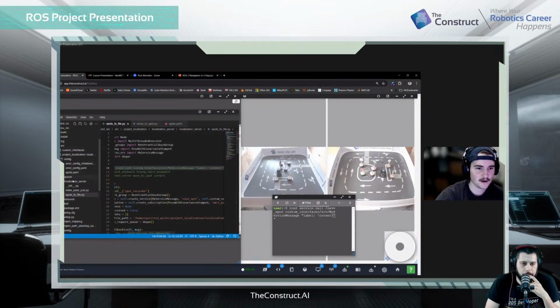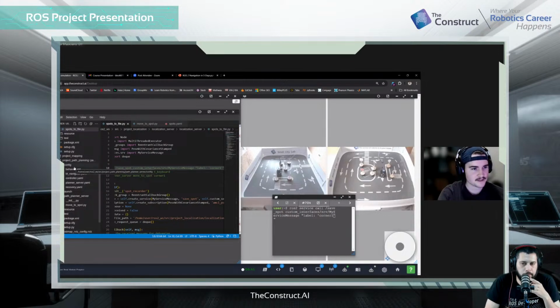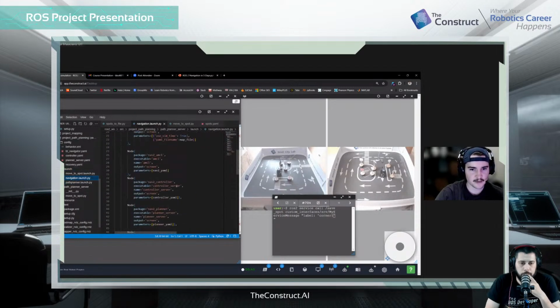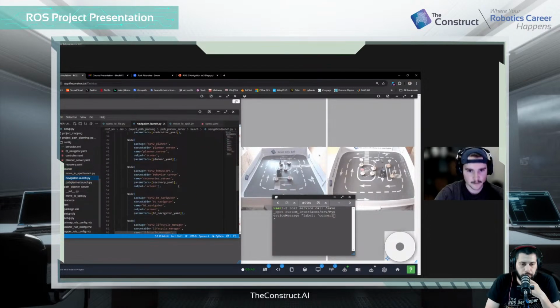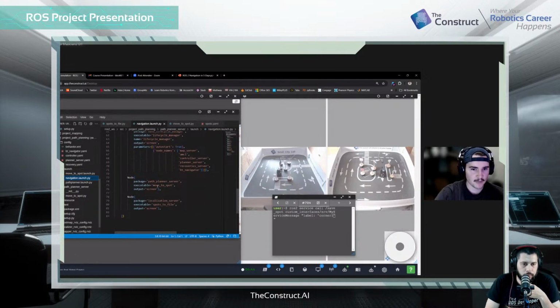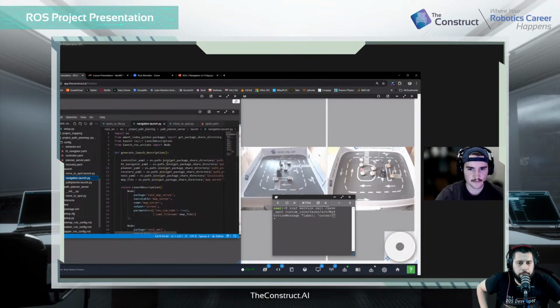I should mention that for my navigation launch file, I have the spots to file script node launching. I have all of the nodes for AMCL, map server, everything launched at the same time. Can better show it here. So I have the map server, AMCL, controller, planner, behaviors, BT, lifecycle manager, and then I have my action client and the service running at the same time, so I can call on any of them while it's running.